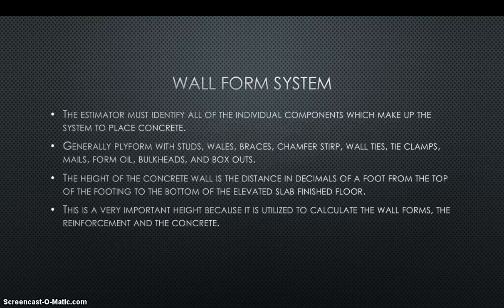So here's a little background on the wall form system. The estimator must identify all of the individual components which make up the system to place concrete. Generally ply form with studs, wales, braces, chamfer strip, wall ties, tie clamps, nails, foam oil, bulkheads, and blockouts.